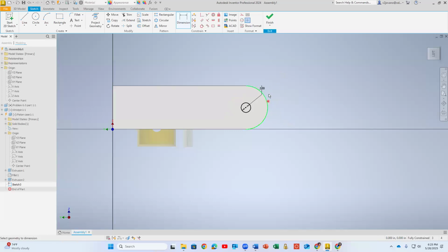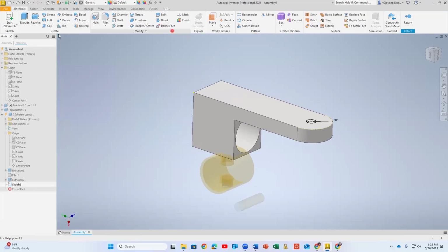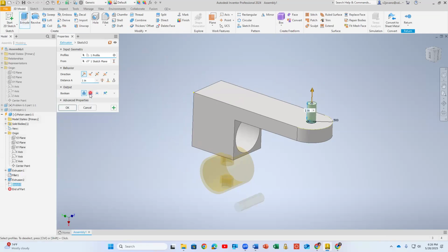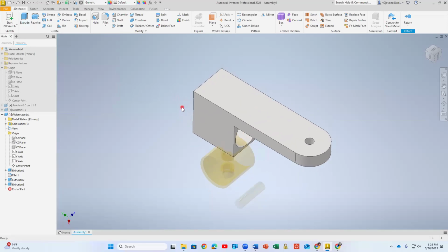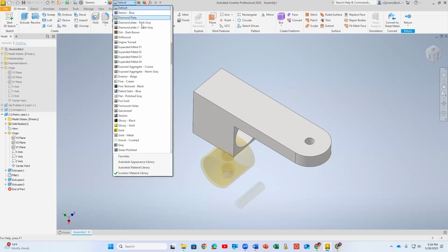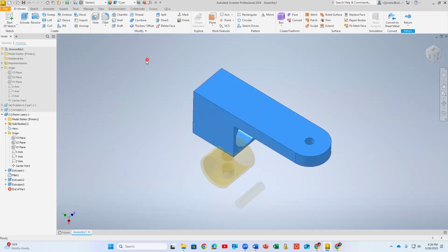And you see, this is yellow now, but if I say escape, I can convert this to construction. I don't need to delete it, I leave it there because it's helping me with this. So with this, I would just add another cut there, extrude, and say Boolean cut, and then say through all. Okay, so you see, I added that one. So this is another part. So maybe I switch the color, maybe cyan, because it's easier when they're different colors when you need to assemble them.